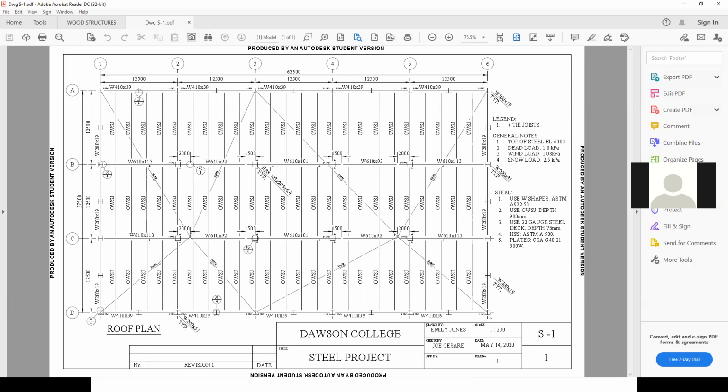Okay, so the top of joist is at 6,000. Yeah, because if you don't tell the guy to drop the top of the flange, how are you going to get the top of the joist to be at 6,000? Yeah, okay. And then my question is, for the minus 500, it means that from B to C, your joist and everything are going to be going diagonally down. Which one? From B to C? No, the joists are just going to be, all you're going to do here, you're going to drop this column, you're going to make it half a meter shorter.